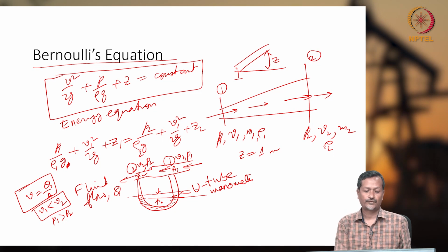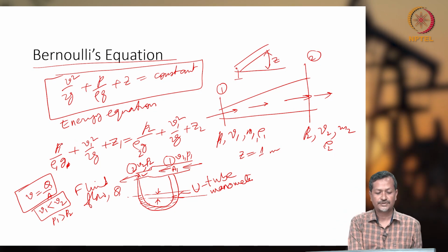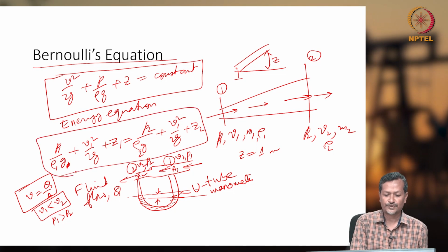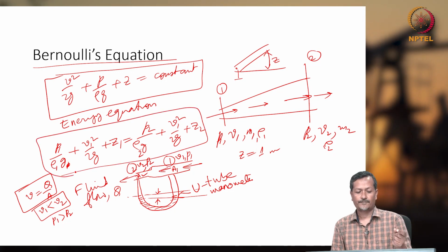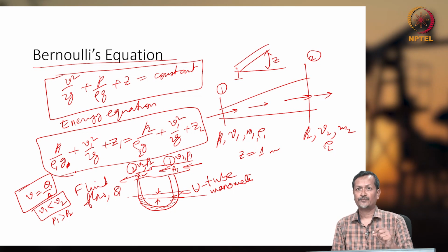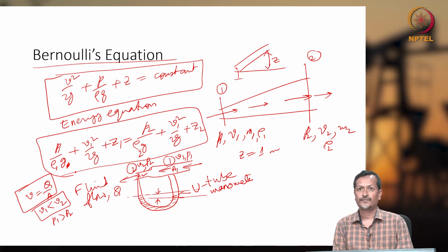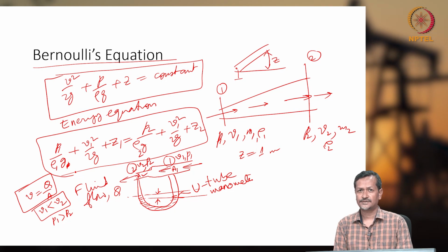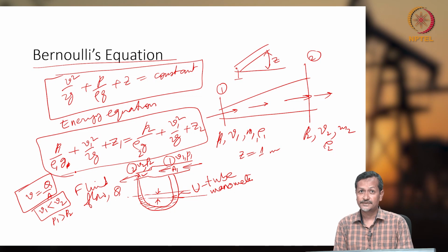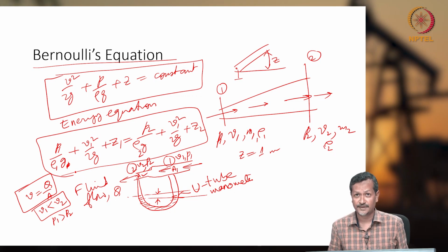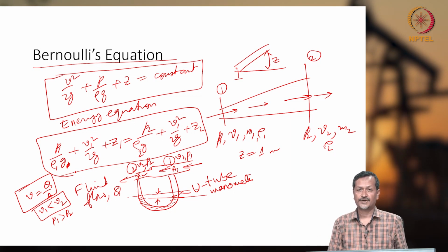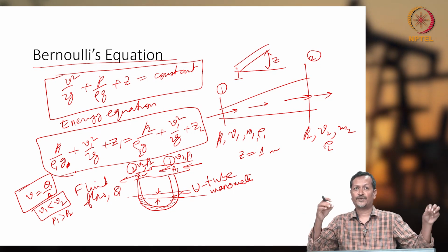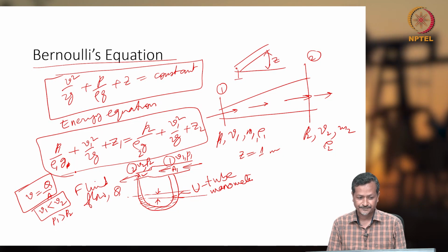So to prove this P1 by rho 1 g equation, this is one universal equation, and to prove this one you can use manometer based fluid flow, and you can check. Many mechanical engineering laboratories in the colleges will have this experiment, because it is the very simplest experiment available to check the pressure drop through pipe, and relation between P1 and P2, V1 and V2 you can calculate.